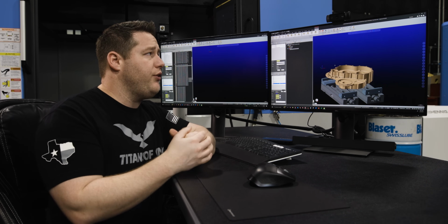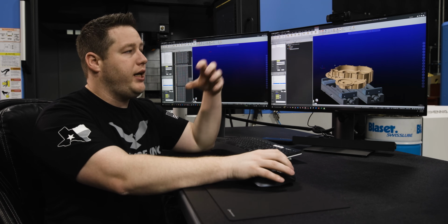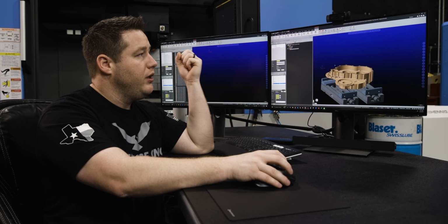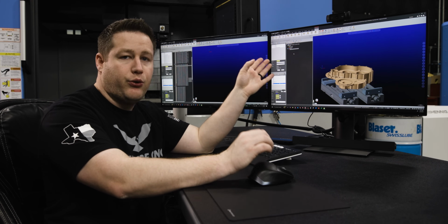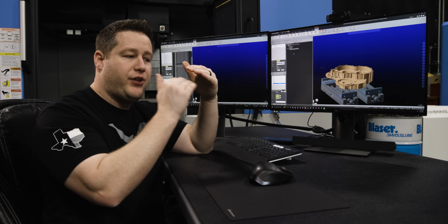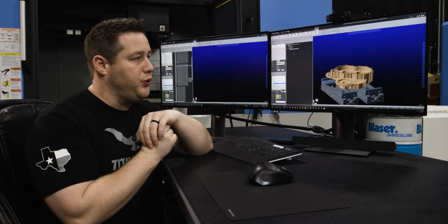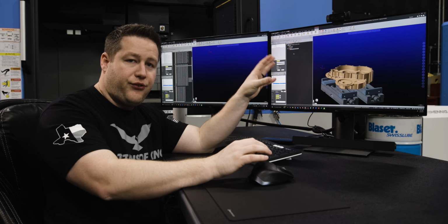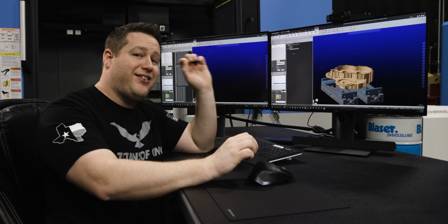But if we want to set up to cut Op2, what we'll also want to do is bring in our fixture, place it where it needs to be, and we also want to create another machine group. So it does need to be separated by machine groups for every operation that you're going to do. So in that machine group, we will select the same part model as our master model. We'll select the same stock.